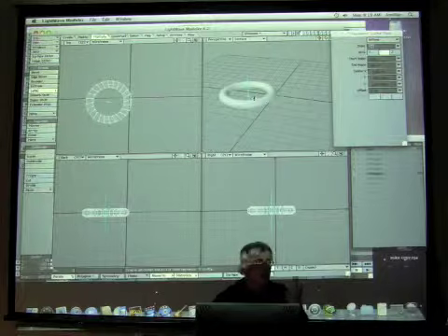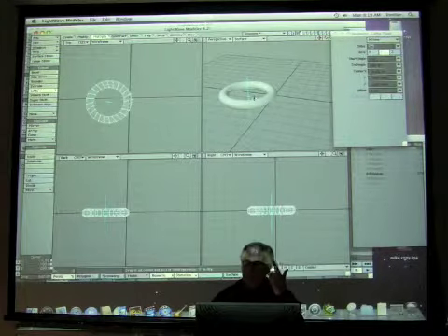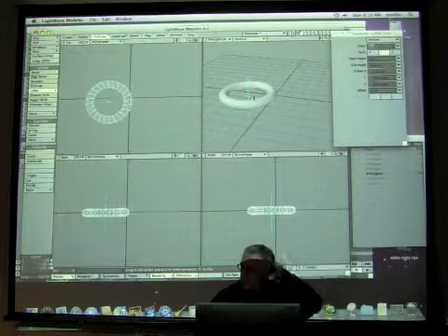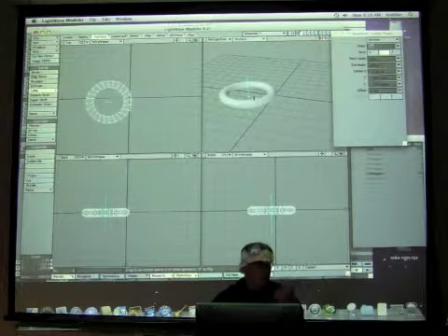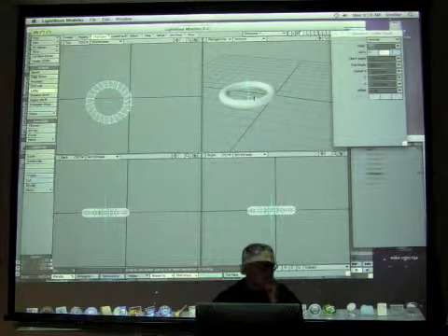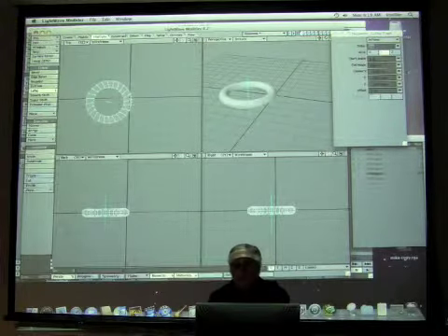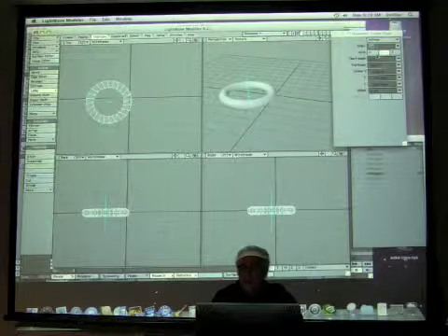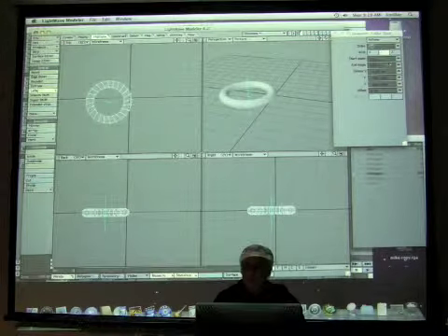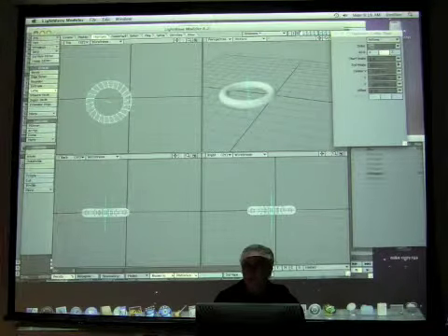Now, what if you wanted to create a spring or a corkscrew-like effect? It's the same principle, only instead of one revolution, we're going to do multiple revolutions, and then change the offset at the bottom. So what I can do now, start angle is 0 degrees, end angle is 360, but I can really crank this up.